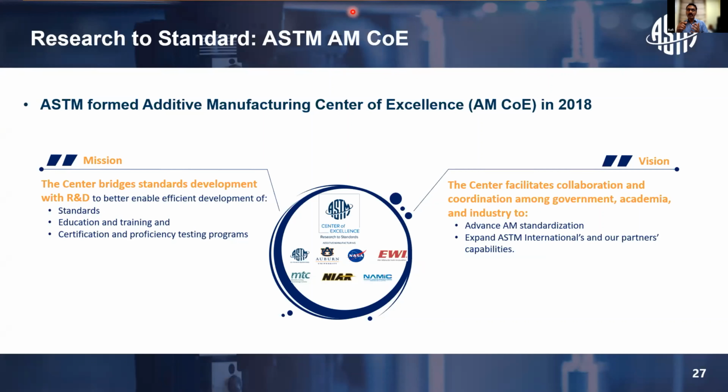In this part family, you have parts with similar wall thickness. You have parts with similar geometrical features. You have parts with similar dimensions. All those things can be considered as a part family, and then you can collectively certify all those parts. So that's the latest, new approach towards qualifying your parts, qualifying your end parts.